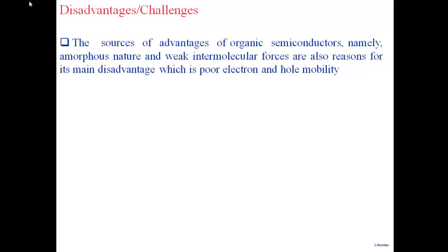I mean, you take it out and you want to see a reading in a few seconds, that would be fine. So you don't require very high processing speed. Even if I have a transistor whose unity gain frequency, the FT that you talk about, is 1 kilohertz, that's fine for many of the sensing applications. I don't need a gigahertz transistor for this. So my point is, low mobilities will limit the kind of applications that you can address, but there's a huge variety of applications which don't need those numbers that you think of. You don't need a mobility of 1,000. You can do very well with 10 to the power minus 3, 10 to the power minus 4, with a mobility of 1.